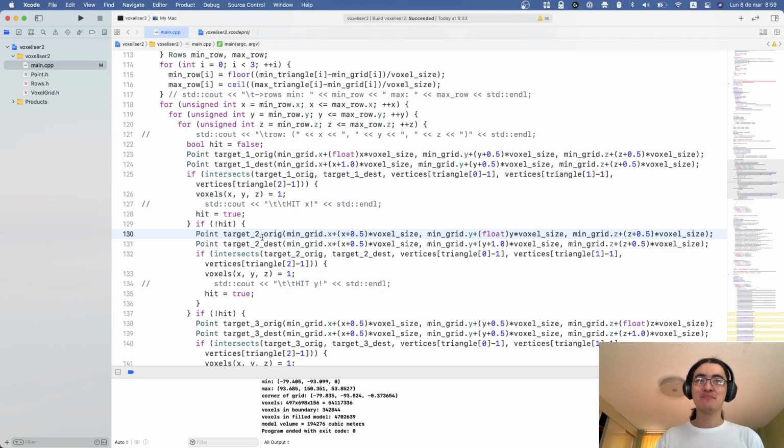Some of you might have noticed that when that happened, the whole bottom of the voxel grid was empty, the whole bottom of the building. So you had something like a hollow model where, when you do the flood algorithm, you might get into the model from the bottom. Yeah, that happens because of the intersection tests when the model is perfectly aligned to the bottom.